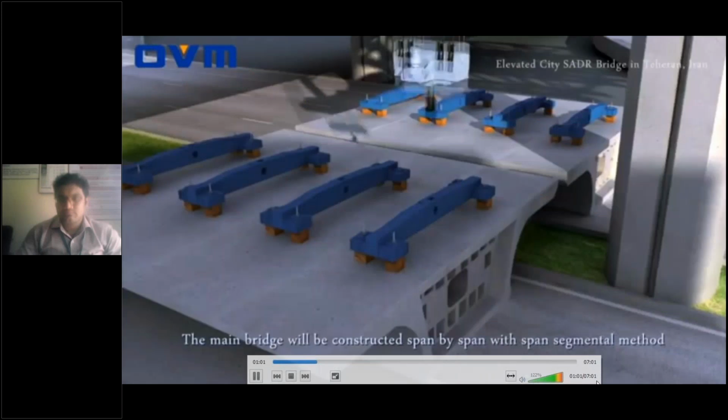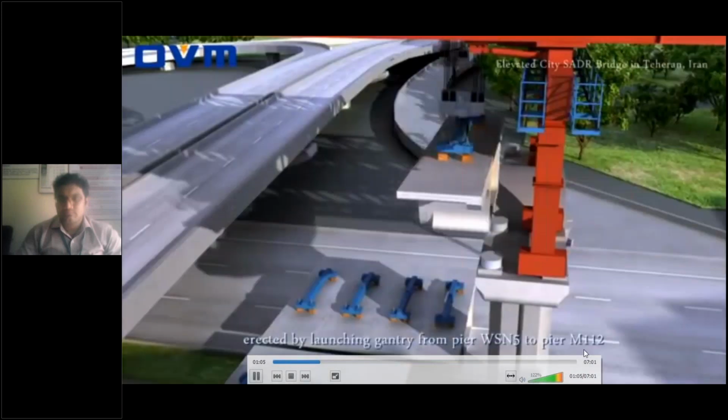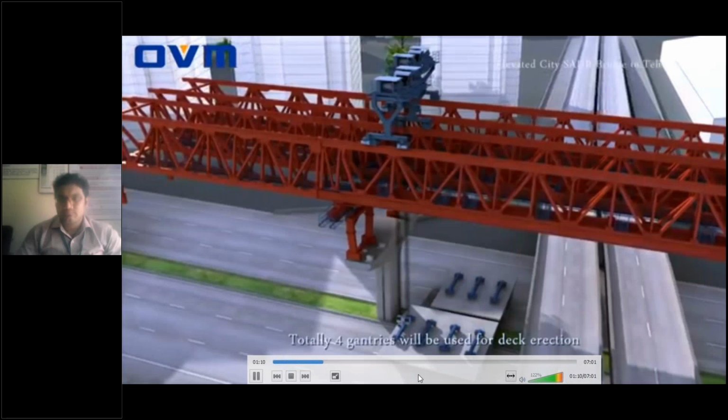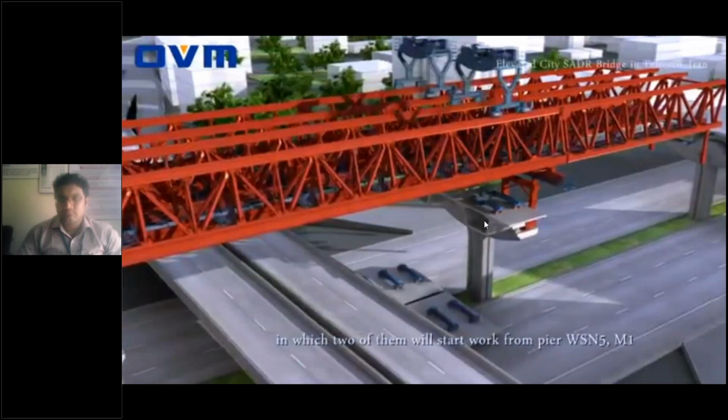erected by launching gantry from Pier WS-N5 to Pier M112. Only 4 gantries will be used for deck erection, in which 2 of them will start work from Pier WS. Here you can observe each segment is pre-tensioned. Okay, after launching every segment, finally, they do post tension.